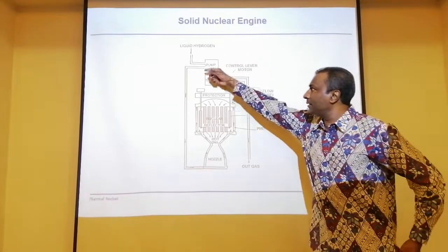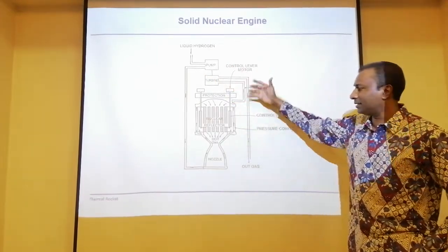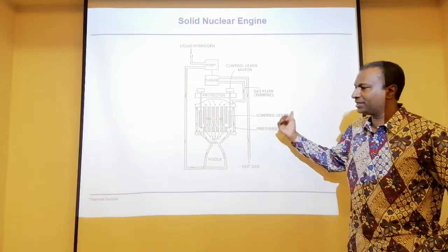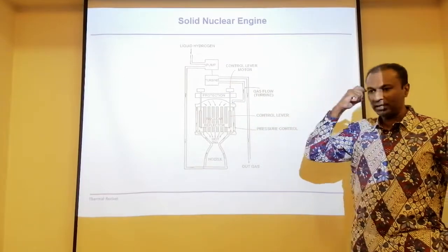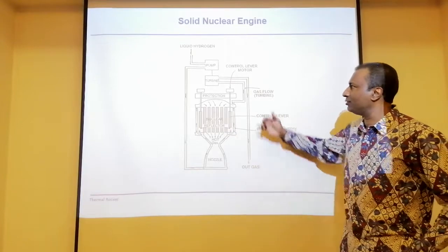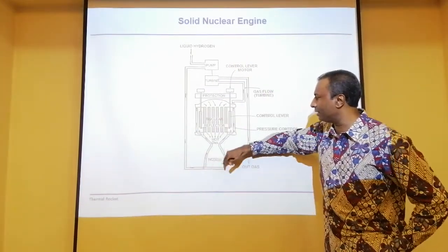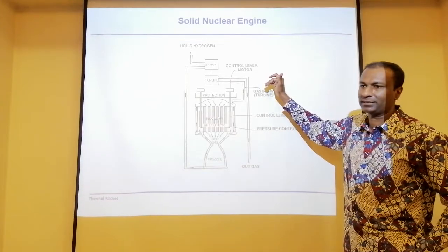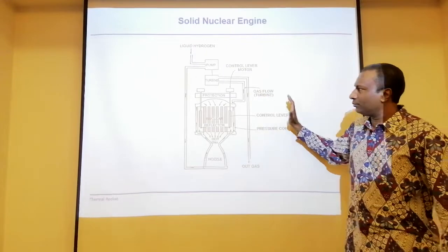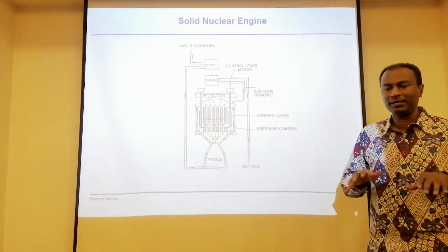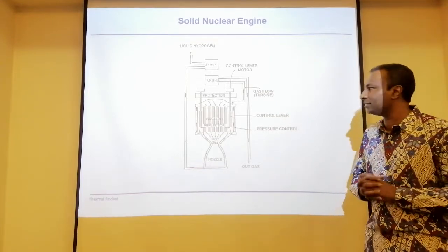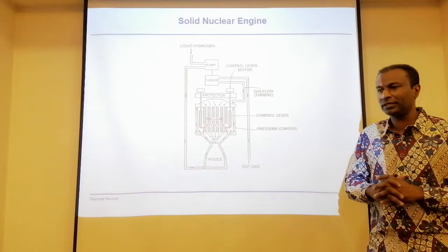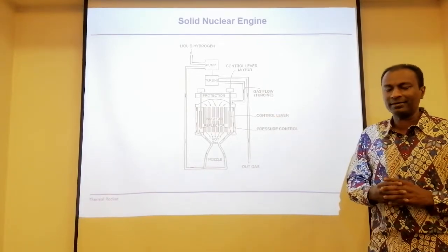If it's liquid hydrogen, you have a turbine, but this is a nuclear solution, which I just want to share. There are nuclear concepts, nuclear engines, which run this way. As we know, when we start dealing with nuclear, there is a huge amount of heat that can be used. So the pumped fuel goes through this nozzle, is heated up again, and then you purge out the gas. So you get a thruster. This is not only managing the heat, but also optimizing the fuel burn. That is important. But remember, nuclear options are not common for our Earth orbit missions. But the reheating of the fuel is also being done even in chemical rockets.